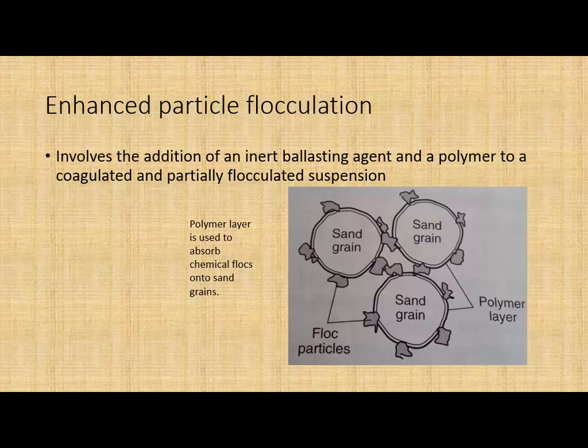And this is enhanced particle flocculation. It involves the addition of an inert ballasting agent and polymer to coagulate and partly flocculate the suspension. And you can see from this picture how the ballasted floc layer works. It combines together to gather the sand grains.